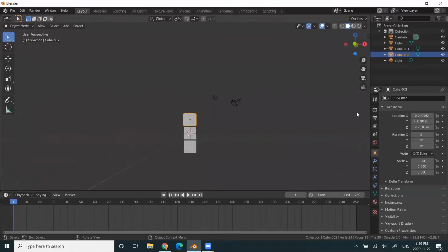Okay, so what I'm going to do is click on these little circles, all three of these, just in case, even though we might only move them along one axis. You'll notice that it turned yellow. That means we set a key, and there's a little diamond here that tells us that we set a key. Now I'm going to scrub forward in the timeline.